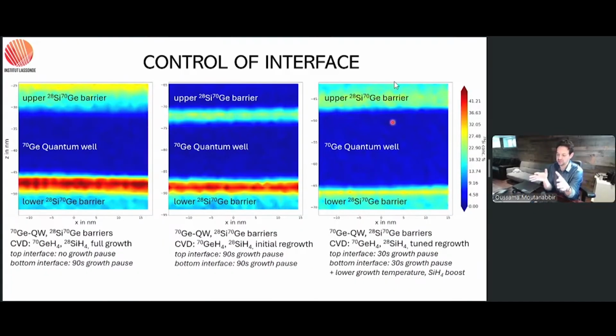So here, what we showed is that by working with ex situ silicon germanium surfaces, we can solve part of that problem. And something I didn't mention, we also modified the hardware of the CVD reactor in a way that we can only supply a small amount of precursor without hampering the growth rate.